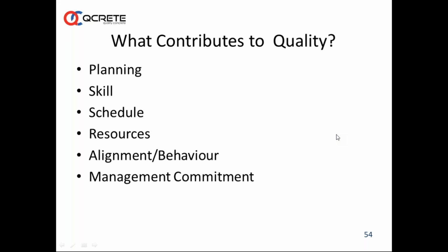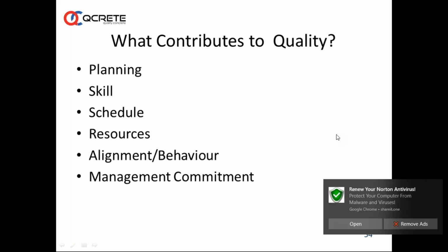Basically you need to have a certain water cement ratio. If you go below a certain water cement ratio, stickiness comes actually. To avoid that, note that if you have very high cementitious content, you have stickiness. Sometimes you have GGBS mixes with high total cementitious content. If it is more, GGBS mixes will also give this kind of property. And most importantly, you need to consult or discuss with the admixture manufacturer if there is any possibility of reducing the stickiness. They can also do this actually.